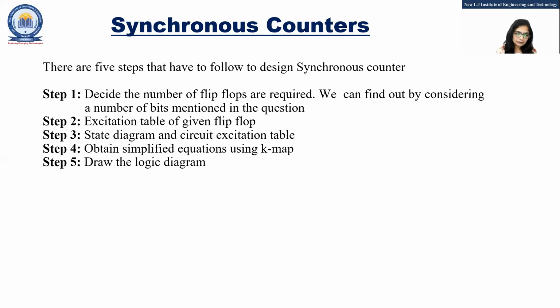Now, step number 3, you have to draw the state diagram and then the circuit excitation table. Step number 4 is to obtain simplified equations using K-map. And the last step, number 5, is to draw the logic circuit diagram using the logic equations.